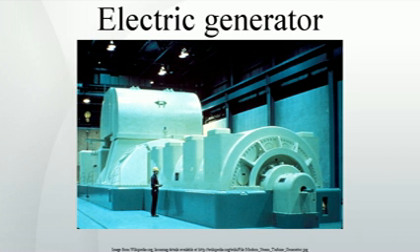Since the rotor field only requires a tiny fraction of the power generated by the machine, the brushes for the field contact can be relatively small. In the case of a brushless exciter, no brushes are used at all and the rotor shaft carries rectifiers to excite the main field winding.